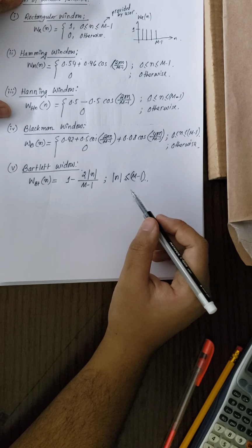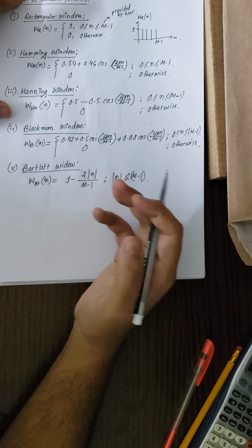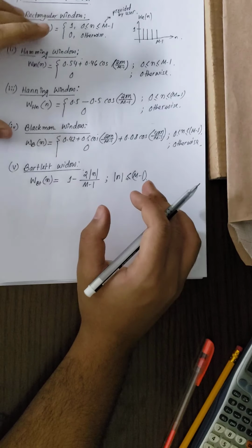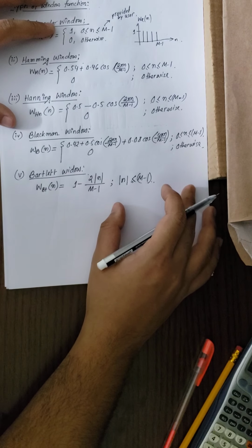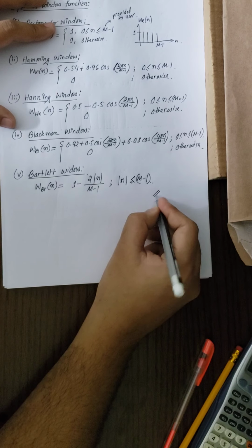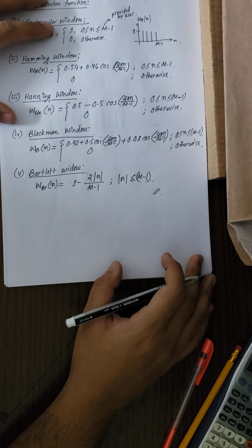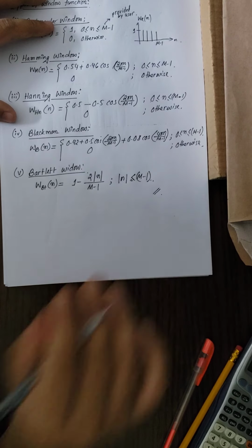So we can solve windowing problems using the Bartlett window, but we need to do a simple step of shifting the result to make the impulse response causal. So this is our theory behind the window, or rather the windowing technique. So let us look at a mathematical example.